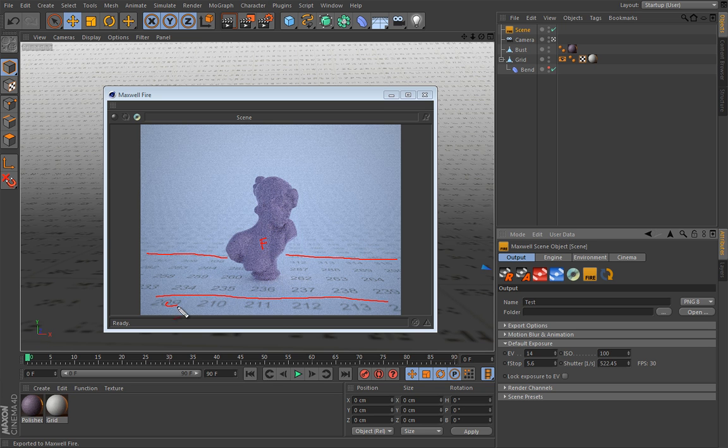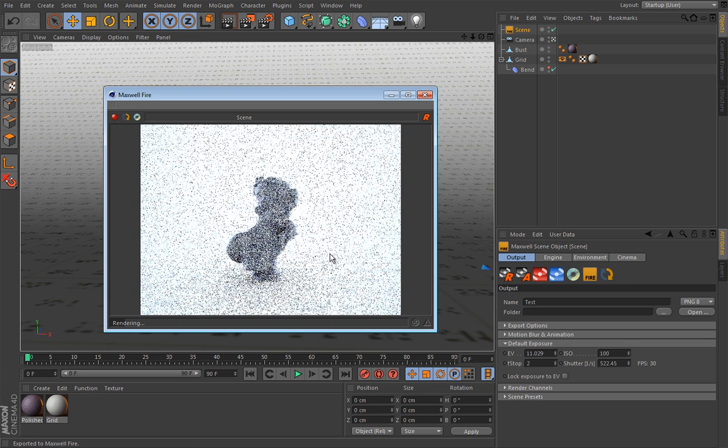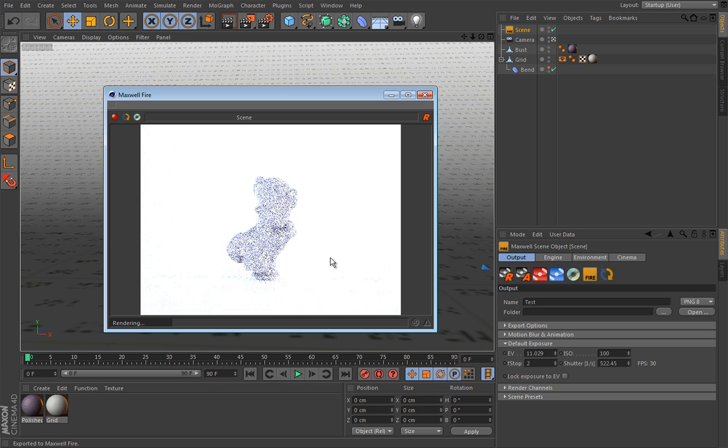This is where blurring occurs, and everything that goes away becomes increasingly blurred. So that is a really important concept. So we said that this f-stop is the main culprit for this blurring. So let's actually lower it to maybe 2 and let's refresh this and see what happens. And this is not what we want.